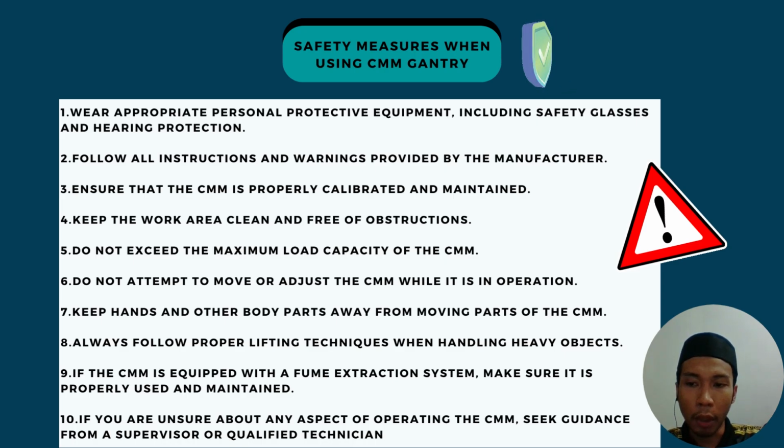Number 9, if the CMM is equipped with a fume extraction system, make sure it is properly used and maintained. Number 10, if you are unsure about any aspect of operating the CMM, seek guidance from a supervisor or equipment technician.